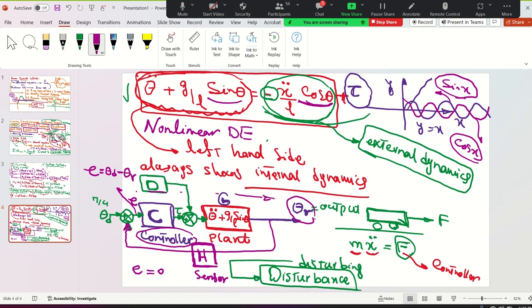The real output is sensed through the sensor, which is compared or subtracted from the input and gives you the error signal. Based on this error signal, we're going to design the controller. It comes here, is summed with the disturbance, goes to the system, and this loop continues until the error signal goes to 0. And can you believe that every day you are using your car cruise system, you are running this loop every day?